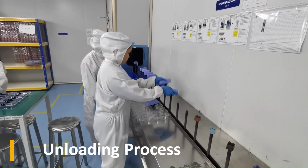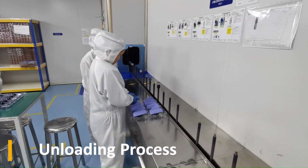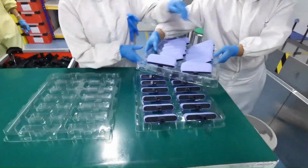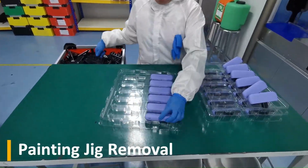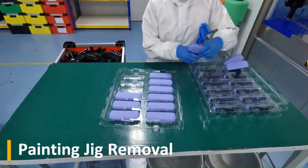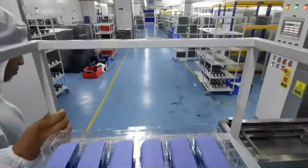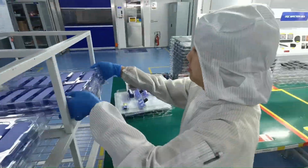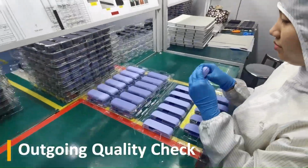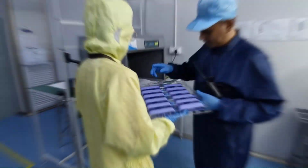After the curing oven, the painted product goes through cooling and then comes out to the unloading area. The painting jig will be removed from the painted product, and the painted product is put into a clean tray. Next, the painted product is ready to be sent to the inspection area. It will be inspected by the outgoing inspection team based on limit samples and confirmed by the QA team.